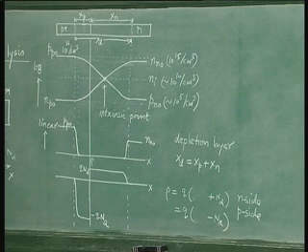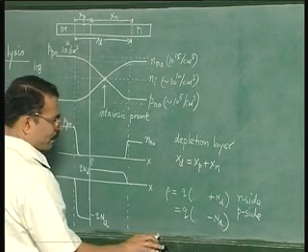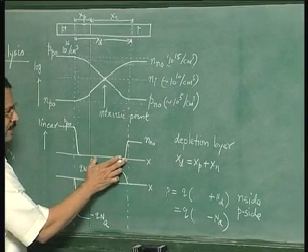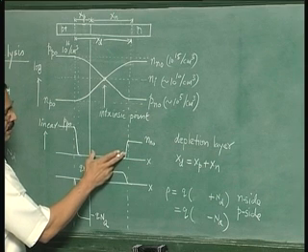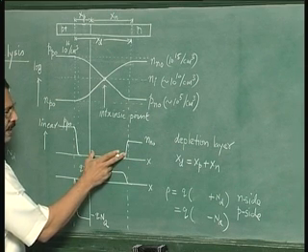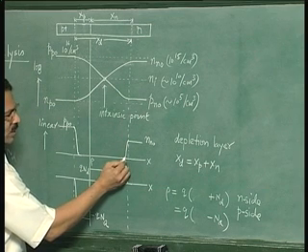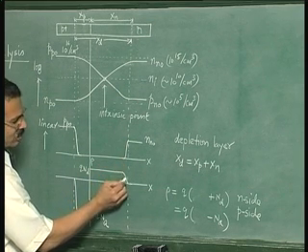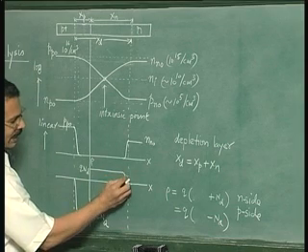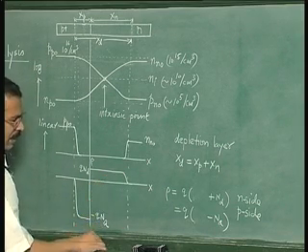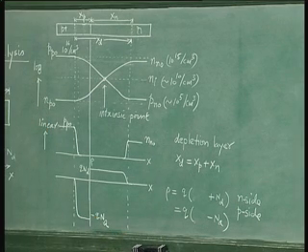Normally what we do is we make what is called a depletion approximation. That is, we assume that this entire region is totally depleted of free carriers, though actually it is this region that is depleted of free carriers, and there is a region over which the variation occurs gradually. So the space charge is changing to 0 gradually here towards the end, but we will ignore this small distance, and for simplicity we make the approximation that is called complete depletion approximation.